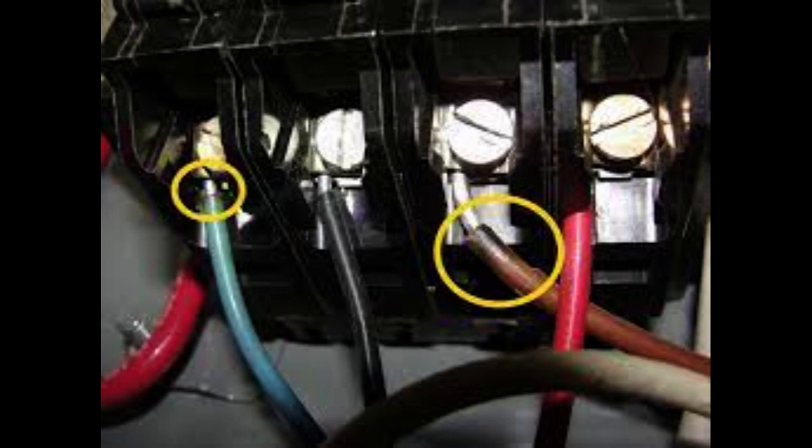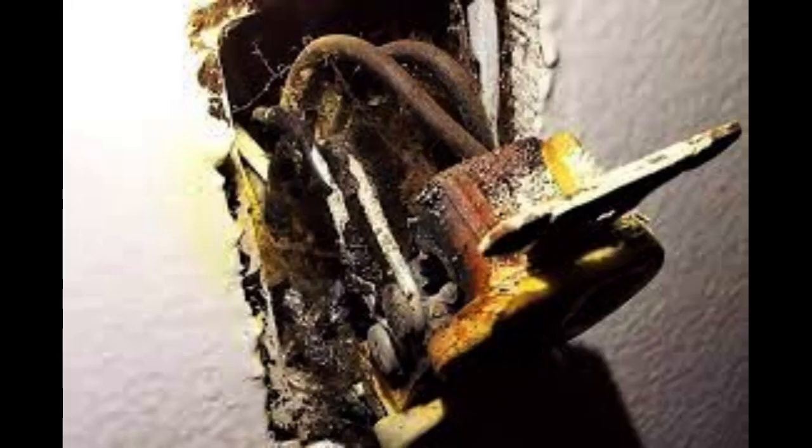B. Branch circuits, connected devices, and fixtures. 1. The inspector shall: A. Manually test the installed and accessible smoke and carbon monoxide alarms. B. Report the type of branch circuit conductors, and C. Report as deficient: 1. The absence of ground fault circuit interrupter protection in all: 1. Bathroom receptacles. 2. Garage and accessory building receptacles. 3. Outdoor receptacles. 4. Crawl space receptacles and lighting outlets.